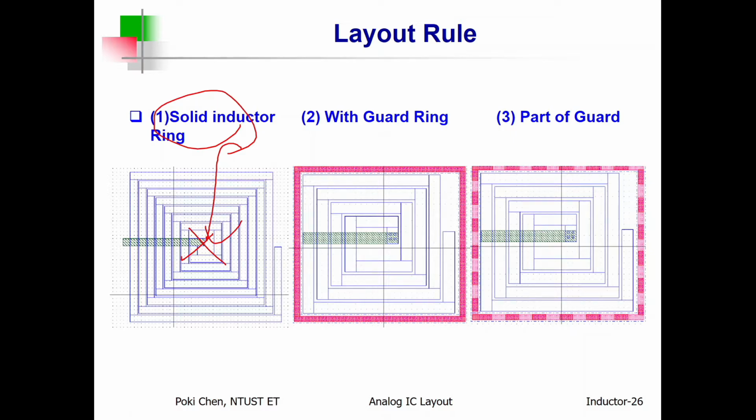It means the inductance will become really small. Don't do any kind of silly layout like this. You need to have an opening in the middle. Okay. Then with guard ring, what is the function of guard ring?